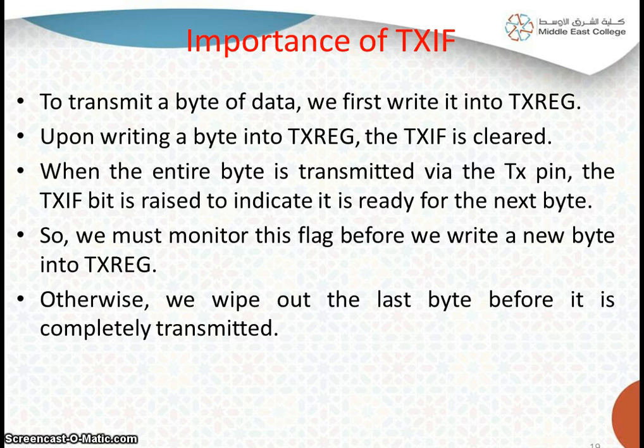When the entire byte is transmitted via the TX pin, bit by bit, the TXIF bit is raised, indicating that the data is completely transmitted and it is ready for the transmission of the next byte.